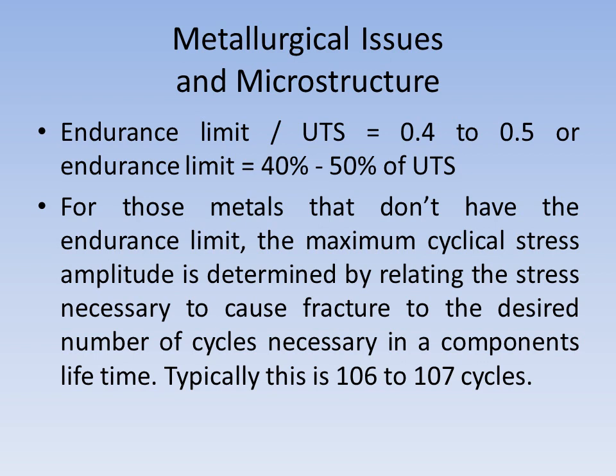This much detail is not necessary from the exam point of view, but it will give an idea and will help you to answer when questions related to some practical aspects are asked. The main point to remember here is that endurance limit is 40 to 50% of UTS. If the endurance limit is not there, 10^6 to 10^7 cycles are fixed and the stress corresponding to it is considered as stress without mechanical damage.